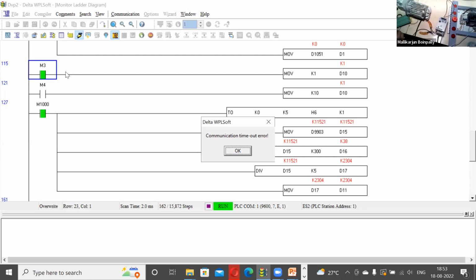Okay, now I'm going to connect this potentiometer. This is one potentiometer. Okay, this potentiometer is having three terminals: 0, 10 and signal. Okay, 10 I have connected to the 10. Ground we need to connect to the ground. Middle one we need to connect to the signal AV1 itself.